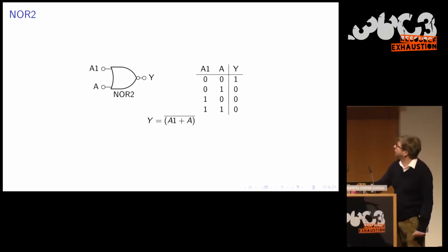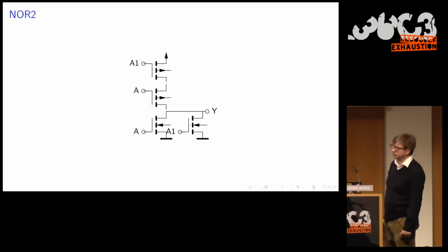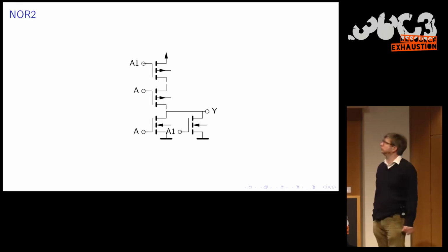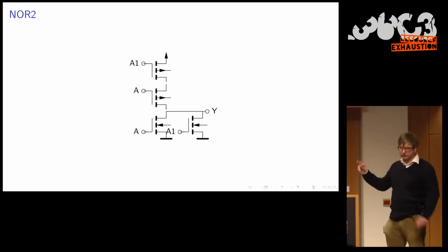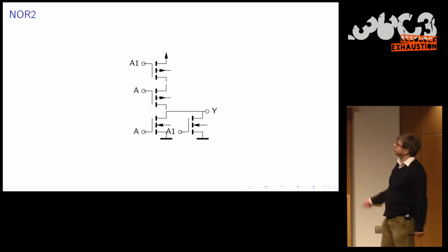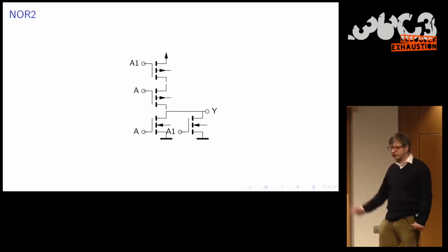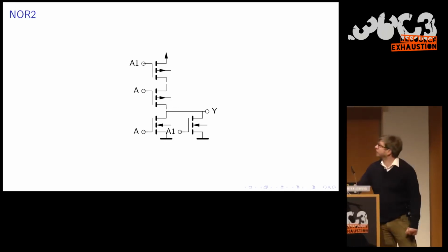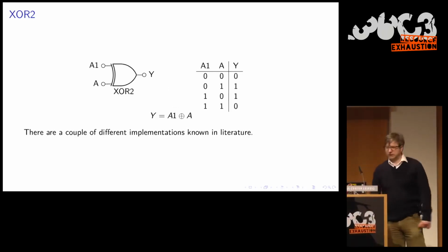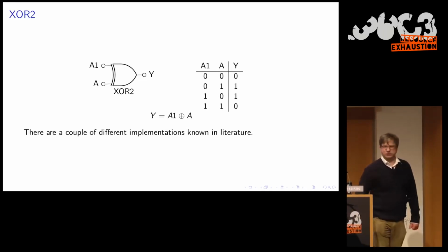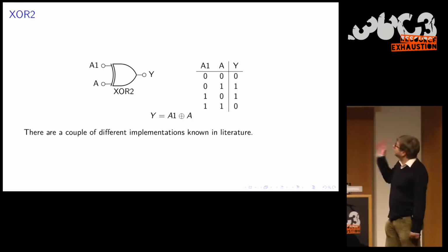And the notation down below again. And here the transistors. You can look at this as mirrored. On the bottom you have the inputs which are parallel, and then on the top the P channels which are parallel. This is an XOR, an exclusive OR.